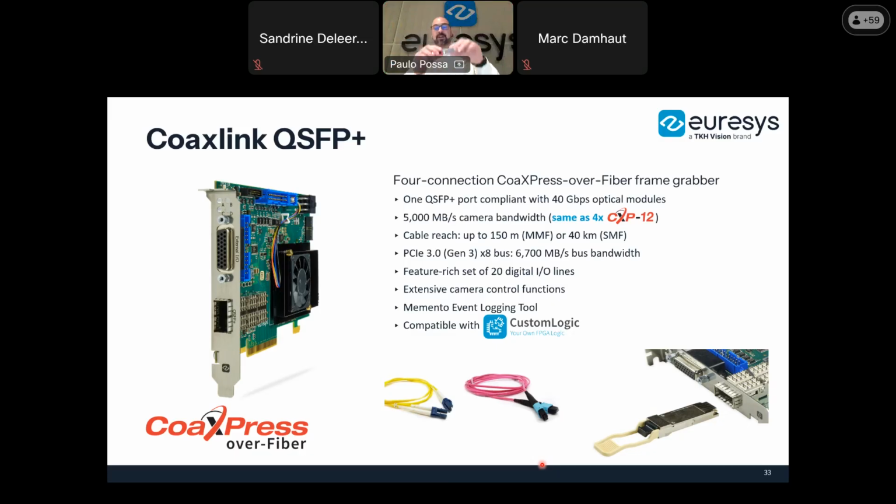Then we have separate optical modules. This one is for 40 kilometers. So this module can do up to 40 kilometers of cable. This one specifically uses single mode fiber, a single pair of fibers with a duplex LC connector. And this cable can have up to 40 kilometers.